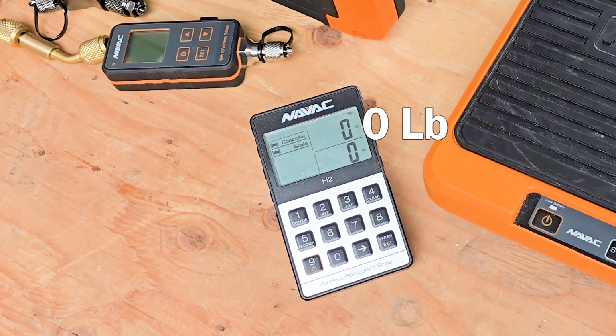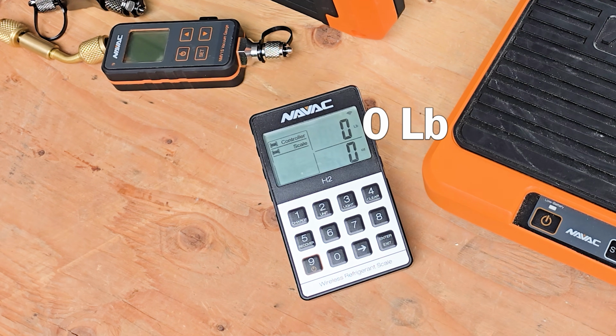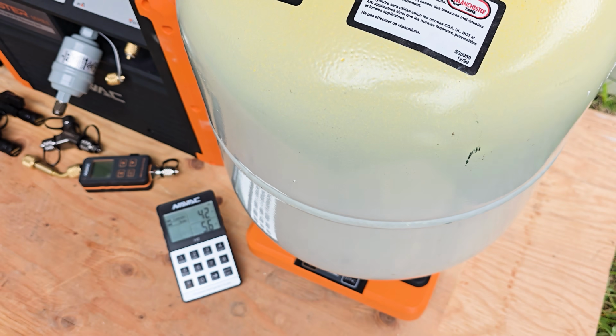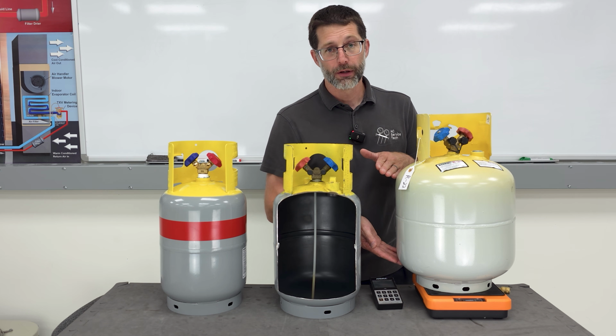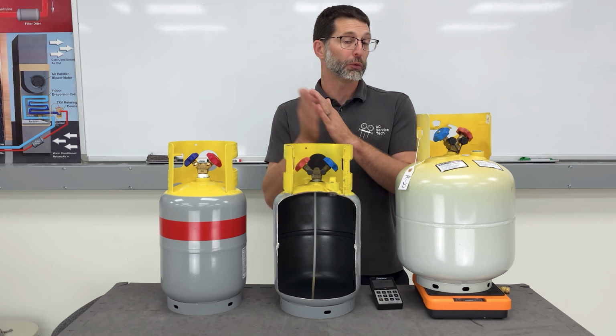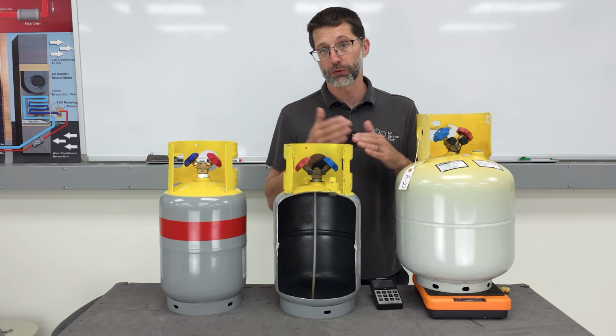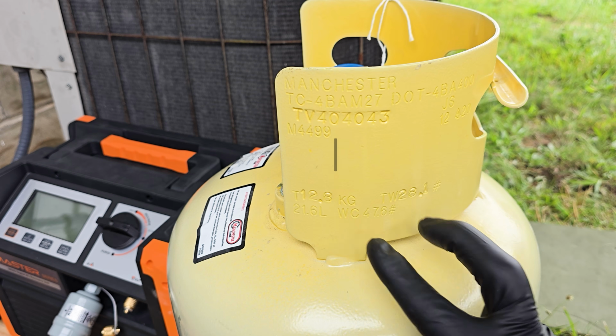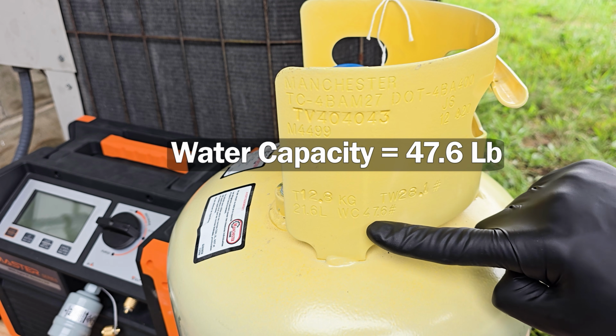And so we would zero the scale out first, turn it on, zero it out, and then put the bottle on. We're going to make sure to not overfill the bottle, and in order to do that, we need to compare the refrigerant to liquid water, and the way we do that is with specific gravity. So on the neck up here, there is a water capacity on the neck. There's also a tare weight.